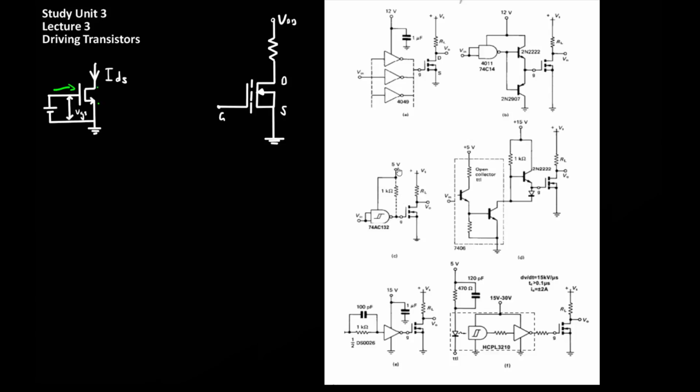To compensate for the limited ability of the device to source current to the power MOSFET, an extra resistor is used in this configuration, which allows additional current to be sourced directly from the power supply into the gate of the power transistor. In this configuration, when the input of the power MOSFET is being driven low, then the current sinking ability of the TTL gate will be an advantage, as the current will be sunk through.